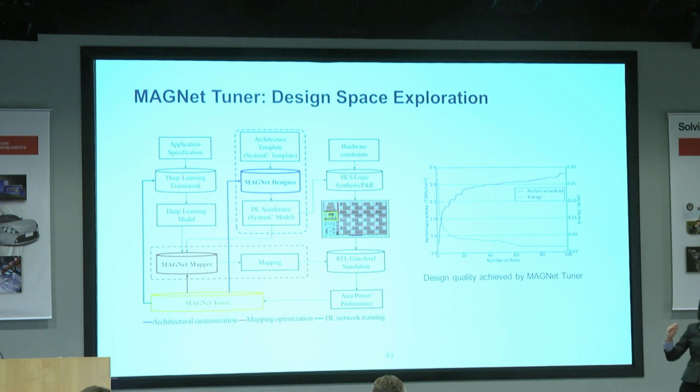But we can get performance feedback reasonably well by using a SystemC-based high-level synthesis flow. We're just running high-level synthesis SystemC simulation, which is basically a C++ simulation in the design process, instead of doing Verilog simulation. For a large-scale system it also slows down, but it's pretty reasonable. We're talking about something like 10 kIPS as a fast simulator. I think that also simplifies the design process reasonably well, at least to find a reasonably performance-efficient one.